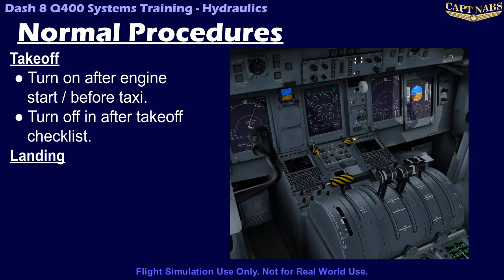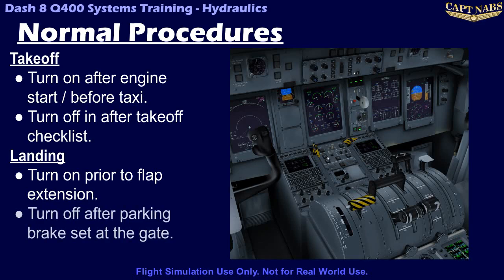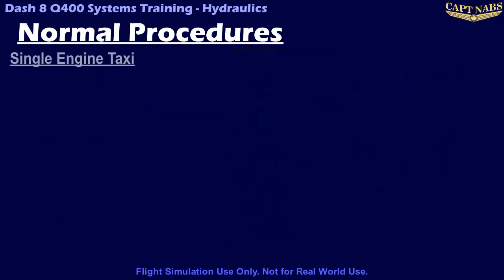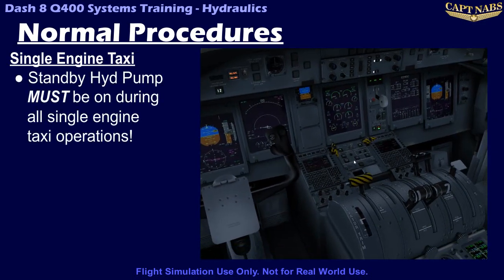For landing, these are normally turned on just prior to selecting the flaps greater than 0. After landing, they are deactivated once the parking brake is set at the arrival gate. If single-engine taxi is to be used, it is imperative that the standby pump be activated manually prior to taxiing on a single engine, whether prior to taxi for taxi out, or prior to shutting down engine 1 for taxi in.